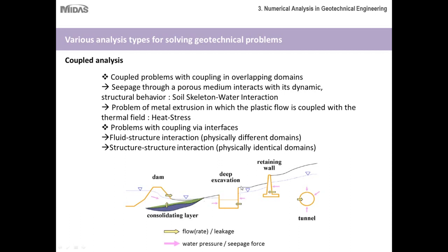The same applies to a deep excavation. So for example, you're excavating over here, you're putting up your retaining walls, but because of the pore water pressure due to this water level here, you have some additional loads that you need to account for. So what you would do is run a seepage analysis to generate your pore water pressure loads, and then you'd apply those loads to your excavation analysis. So essentially what coupled analysis allows you to do is to factor two different analysis types into the same project.